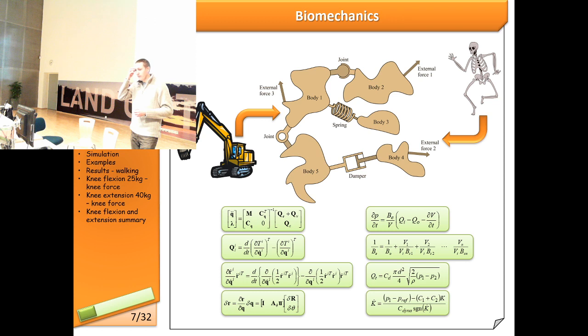And these are the equations of motion that you probably know by heart already from the course. Basically you have the mass matrix, you have the velocity vectors, you have the stiffness matrix, and the damping matrix. All of that combined allows you to solve for different quantities. So depending on what you know and what you don't know, you just solve. You could solve for forces, knowing, for example, motion, and knowing some other elements, or you could solve for the motion knowing the forces applied to a body and knowing the inertial properties. And it's up to your needs what you are going to solve from there.